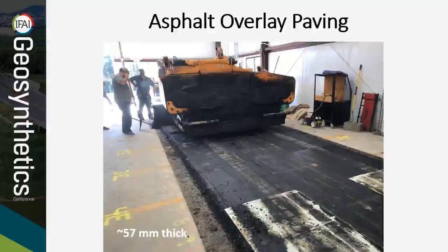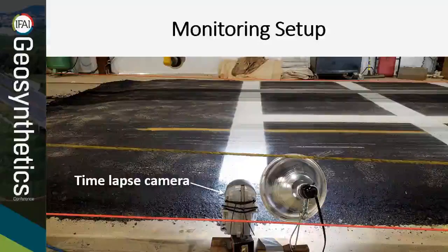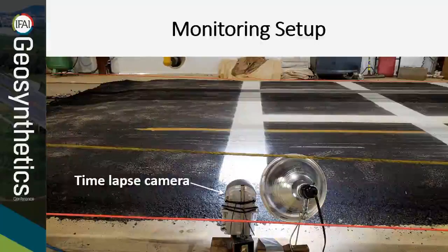The entire pavement surface was overlaid with a single lift that was about 57 millimeters thick. A white stripe was painted on the road surface directly above the transverse crack to help make the reflective crack more evident. A time-lapse camera was set up on each crack to take photos every 15 minutes.